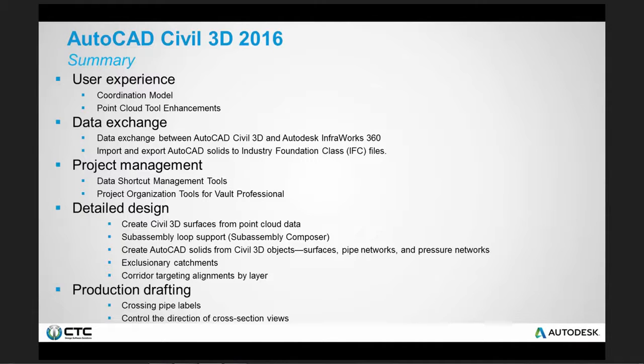The data exchange between Civil 3D and InfraWorks. I believe in our InfraWorks new features, we're going to have more on that. That's some really impressive stuff there, but again, it's a lot of data pushing back and forth, and it takes a few minutes here and there, and it's a little slow to demonstrate, but some very cool tools there. The IFC files, standard files that can be pushed in and out of Civil 3D. The data shortcut management tools, I think that's really a big one for people, especially with larger projects that are spanning perhaps a couple years.